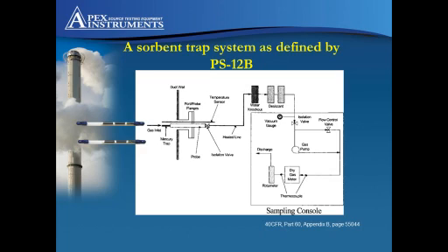The sample gas then flows through the probe, down the heated line to a moisture knockout, creating a dry sample. The sample is then sent to the dry gas meter, which records the sample volume so it can be compared to the volume of mercury collected to produce a time-weighted average value of the mercury sample for any particular period of sampling time.